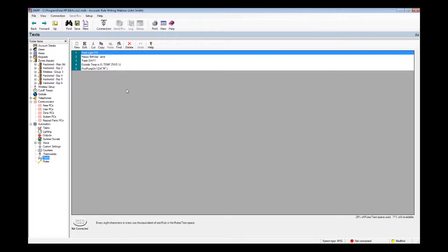So if there's a piece of equipment that we currently don't integrate with directly, but they do publish their RS-232 protocol, if you know what ASCII strings this piece of equipment is expecting to see to do different operations, we can recreate those strings here in ElkRP and then send those strings out our M1XSP, our serial port expander, to the piece of equipment that has an RS-232 port on it.